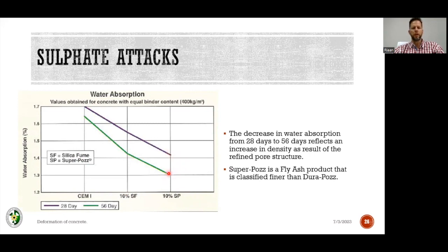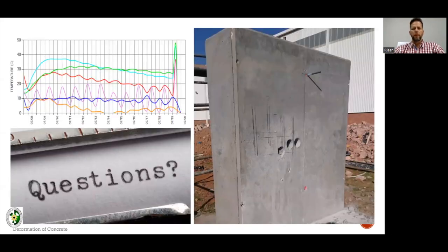So if you keep this as low as possible, you also aid in preventing sulfate attack from being as fast as it could be if you have a very permeable concrete or a weak concrete matrix. The next item we discuss will be